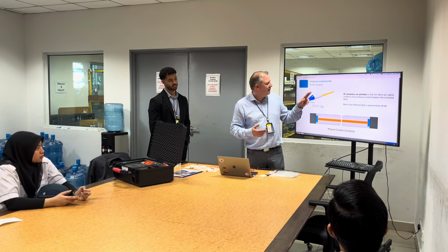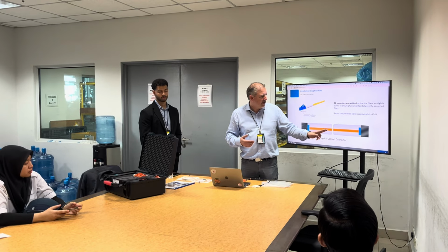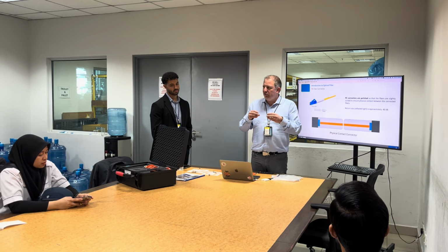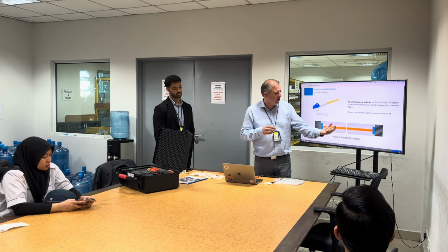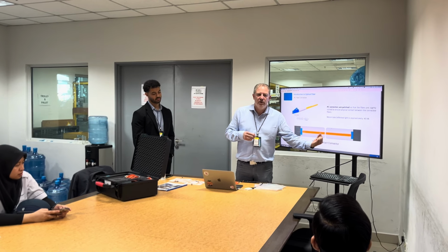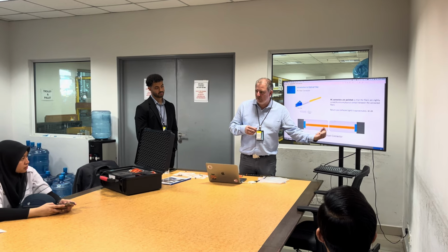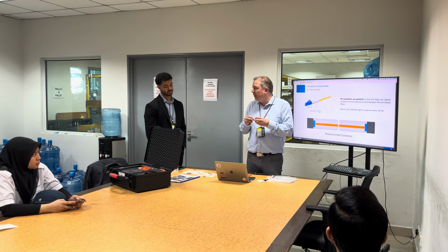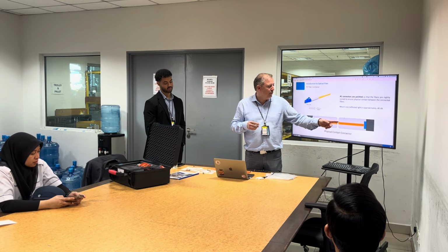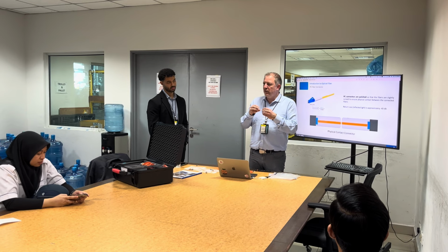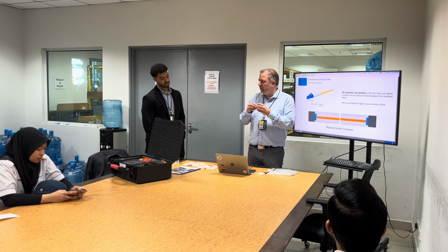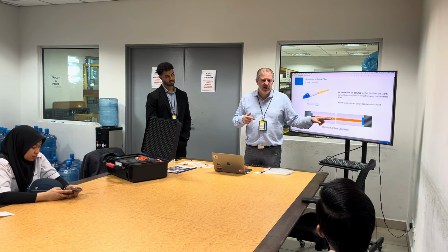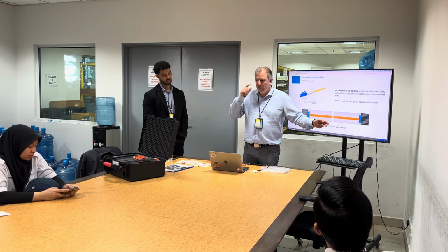So that's an example of a PC fiber. They have polished faces, and the purpose of the connector is to make sure you have pressure, so you maintain physical contact. Most of the time you have a little spring in the connector to maintain physical contact. And the purpose of the connector is also to guarantee perfect alignment, so you have core-to-core perfect matching, and the maximum of light will go through.